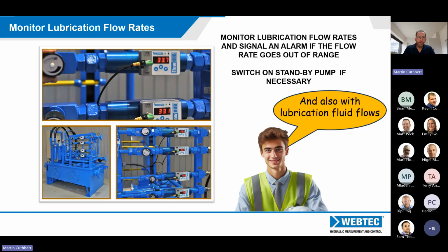That equally could be applied to a lubrication example. So we're monitoring the lubrication flow rates for a large bearing. If that bearing isn't getting enough flow, then that's potentially very dangerous to the life of that bearing. So we could then switch and trigger maybe a redundant pump system to then deliver flow if the first system is failing.